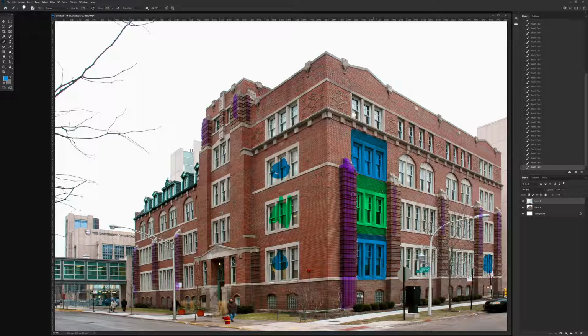That means that there might be some brick going in behind this column. In fact, it might be smart to bring the brick out halfway up the column, like this. The reason for that is that we would then be able to place the column on top.